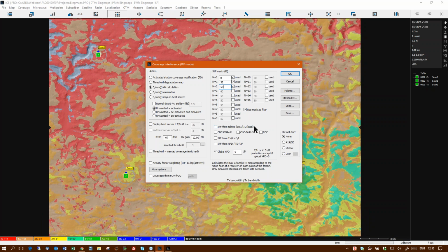You can pick up IRFs from ETSI specs, but in order to do that, your systems that you're using here, Telecom needs to know what these actually are. In the case of this one, these are just generic 25 kilohertz, let's say business radio, PMR radio base stations, nothing exciting. So these are Nyquist 25 kilohertz blocks. But if you're doing microwaves or something like that, and you've got the thing defined enough for Telecom to know what it is, it'll pick it up from tables.